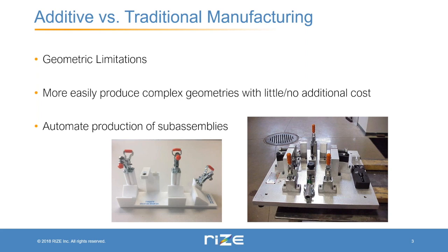This is because with traditional manufacturing, you'll normally be using flat milling tools or machining devices that create flat creases, and this makes it easy to create flat geometries or simple curves on traditionally manufactured parts, but it's much more difficult to create narrow or complex crevices or combinations of complex small pieces on a part.